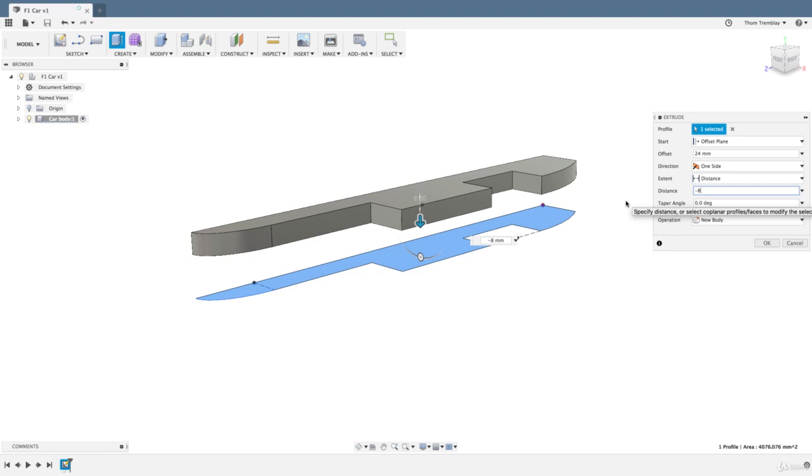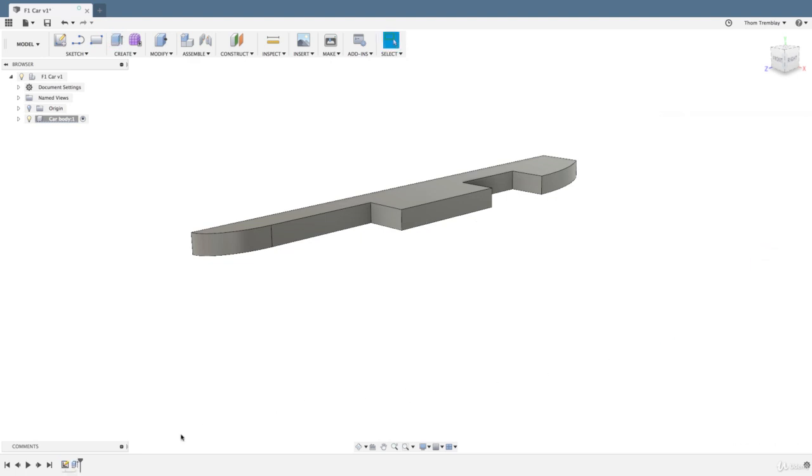There are several different approaches you might consider taking, including just creating your initial sketch on a construction plane elevated that high, or creating the next series of sketches at the bottom and extruding up into the body. Any are viable, and it's really up to what you're trying to accomplish. For now, I'll click OK, and we'll add the extrusion to the timeline and create a solid model.